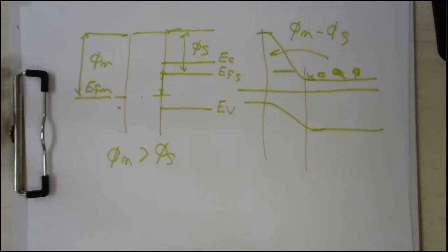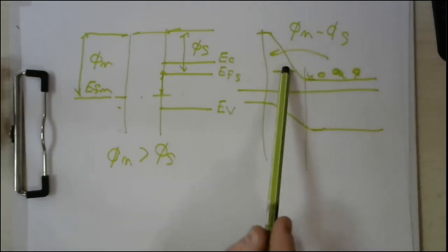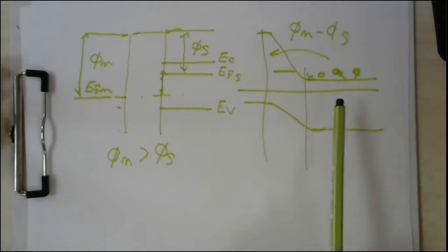If you have a good memory, you will remember that this is typically like a p-n junction. In a p-n junction under thermodynamic equilibrium, if you remember, my dear students, no majority carrier can move because majority carriers see some sort of a barrier, which is the built-in potential, and so they are not able to move.